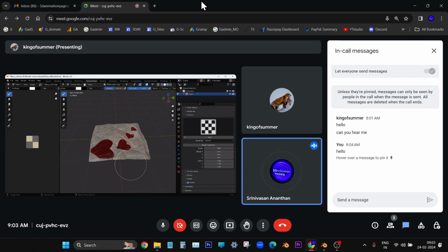Just now you went image save as. Always don't forget to save the image, because Blender won't save the image. You have to deliberately go to the image editor panel on the left side, image save as, PNG format, 16-bit, compression 0, name it wherever you want to save it. You remember, I think we created a directory in which assets folder, textures folder, render output folder, all those were there. So inside the textures folder we have to save it. So you would have saved it inside the textures folder only, I think.